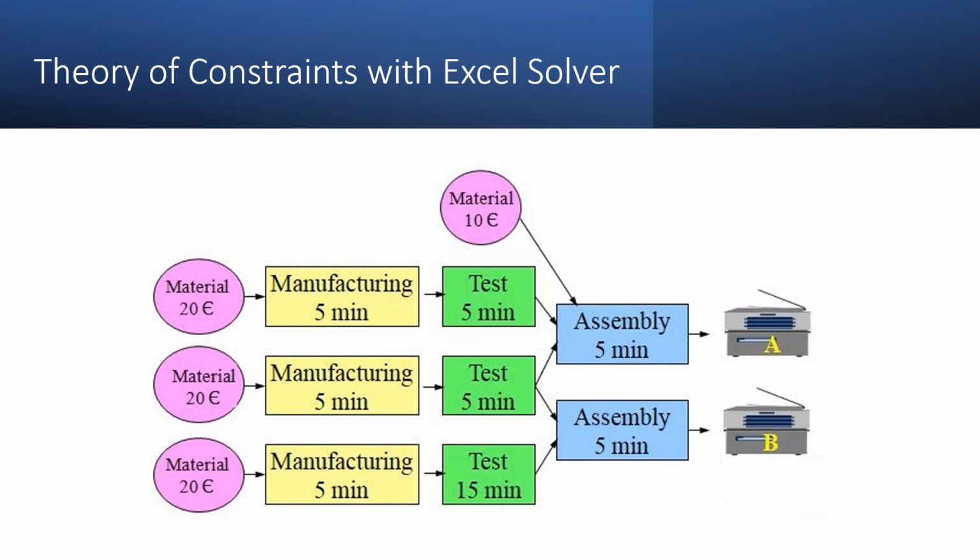With this simple value stream, to produce products A and B, we want to illustrate the way to maximize profit, taking into account the system constraints. Each product is made by assembling two subassemblies, one of them common to both products. The process consists of three sequential operations for which there are special purpose workstations with a corresponding operator each trained for the specific job. Manufacturing, test, assembly.